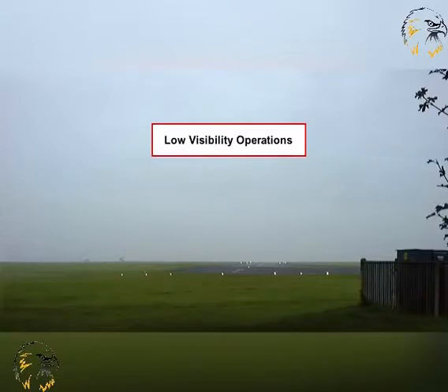In order to permit all-weather operations, for example low visibility takeoffs and landings, procedures have been established to provide track guidance and terrain avoidance for departing aircraft. Where track guidance, terrain clearance and special equipment is used, vertical displacement guidance for aircraft arriving at aerodromes is also provided. Low visibility operations are defined by ICAO as takeoff and landing operations with an RVR of less than 800 metres.